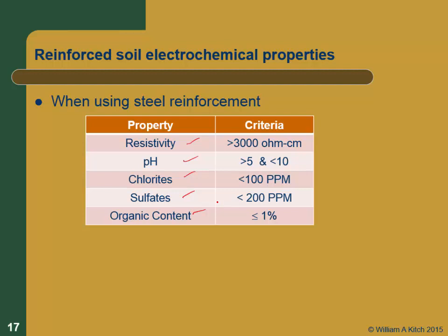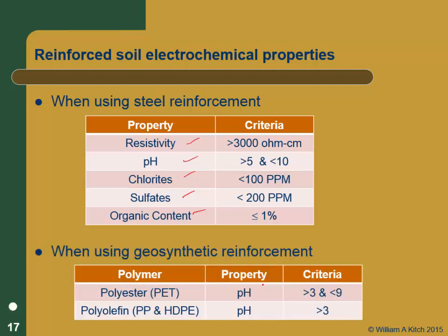So we basically want a non-reactive backfill. You don't want to be putting highly active backfills in with metal reinforcements. We'll talk about how we protect the metal when we talk about the reinforcement properties in the next section. And these generally aren't difficult to come up with.